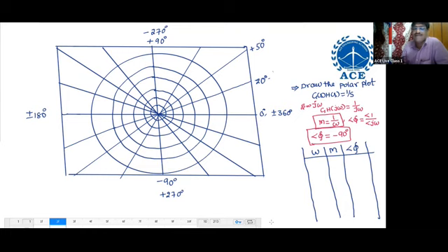Relative stability. Anywhere we find gain margin and phase margin, we are checking the relative stability. From the polar plot we can find the relative stability, as well as from Nyquist plots and Bode plots. Even in root locus, since we know the poles' path, we can directly find the relative stability.